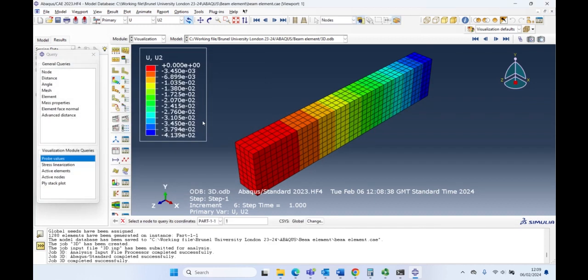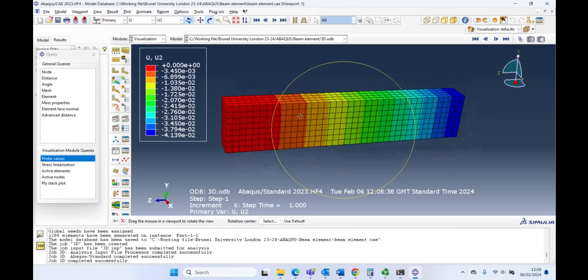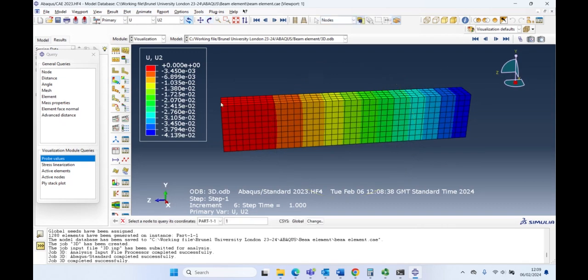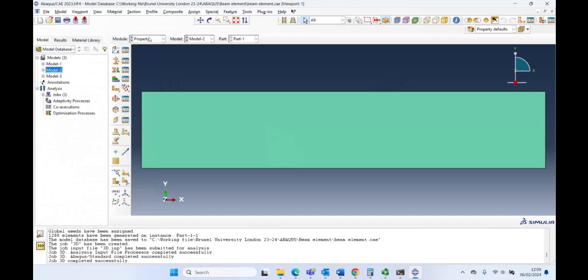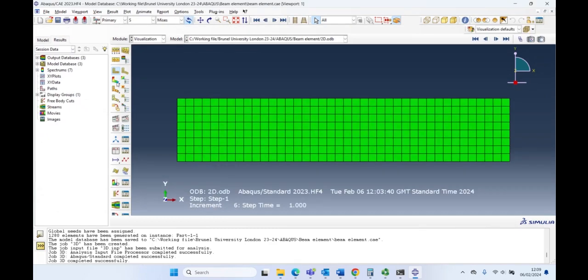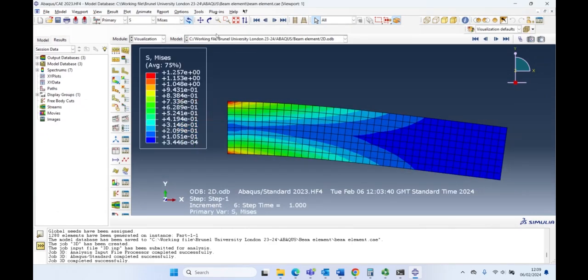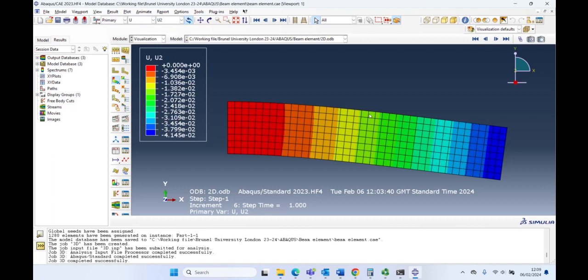Now there's something we haven't done. If you really want to know the deflection on the beam along its length, let me give you an example. I want to model 2, for example. Double click, and here you go to model 2. Okay, then go to Show, and that is your 2D. So if you click here and you want to know really the deflection along, you see the deflection in the Y direction along all the lines here.